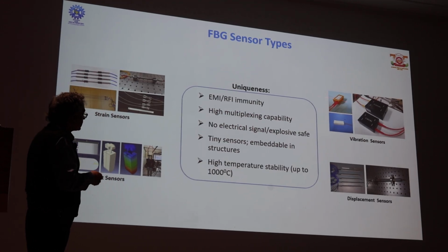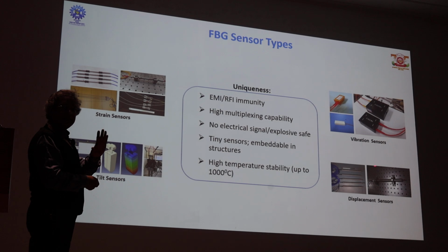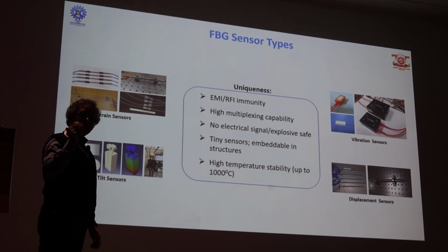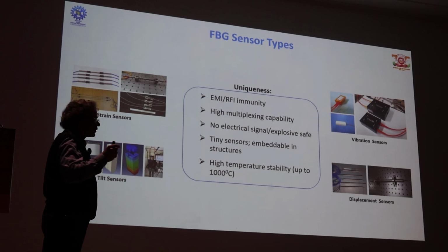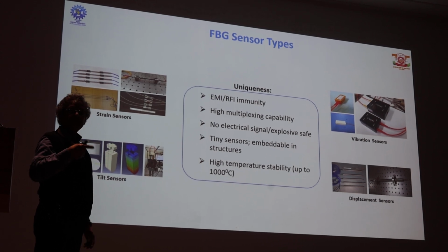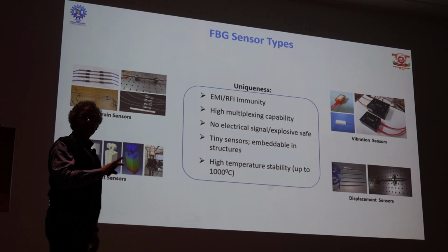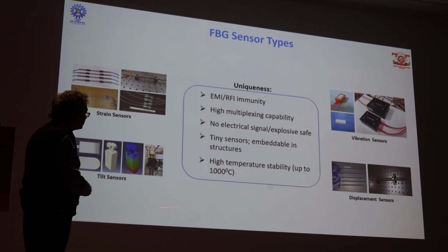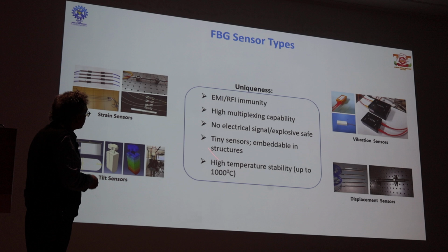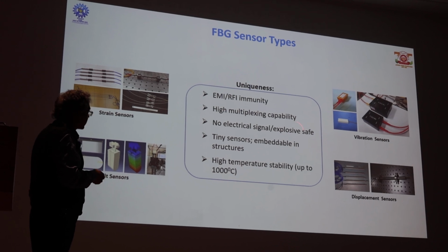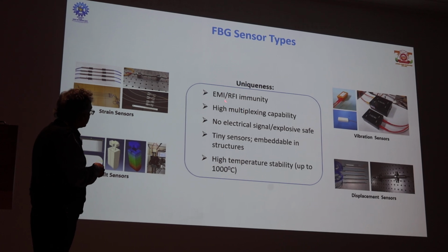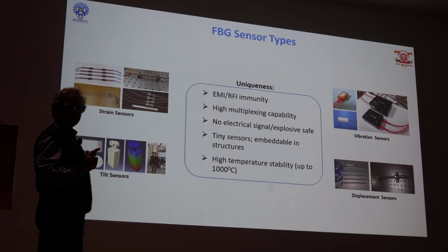So you see, now basic physics to the engineering part. Once you have your sensors at hand in an optical fiber, you only have to incur a strain or temperature change, or pressure, or vibration, whatever it may be; ultimately it will be either in terms of strain and temperature. So you can devise all sorts of strain sensors and tilt sensors depending on the application. Now the uniqueness of these sensors, and why people are now venturing into this, is that they are absolutely EMI and RFI free.